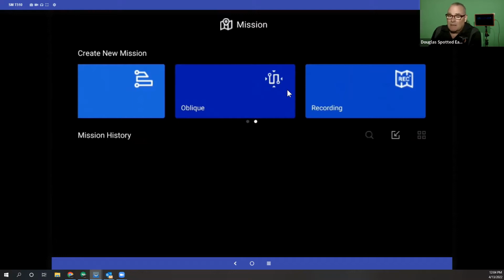At the end of the day, let's say that you do use it and you come up with all these extra images. When you drop them into a tool like Pix4D Mapper or into Leica Infinity or 3D Reality, some of these different tools, because there are so many repeats of the same pixels and similarities in the lat long data or the GPS data that's embedded in the metadata of each photo, you're going to increase your errors. So you will not have a measurable result at the end of the day. So I wanted to point out, we're just going to ignore oblique entirely for this session.